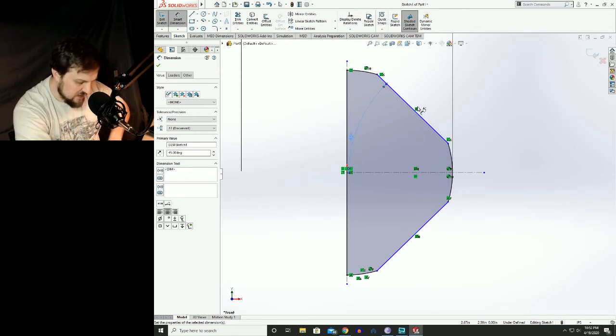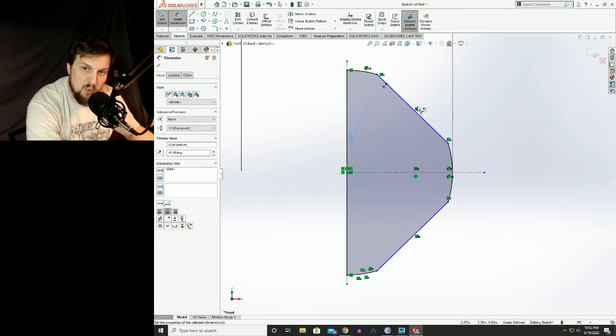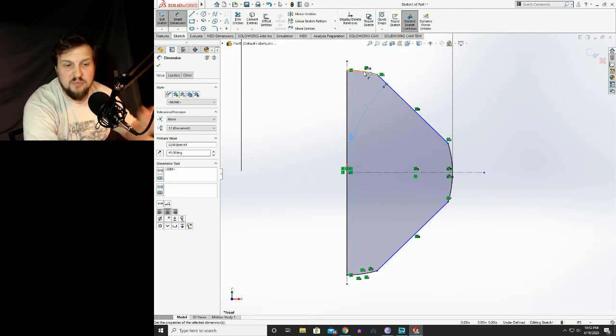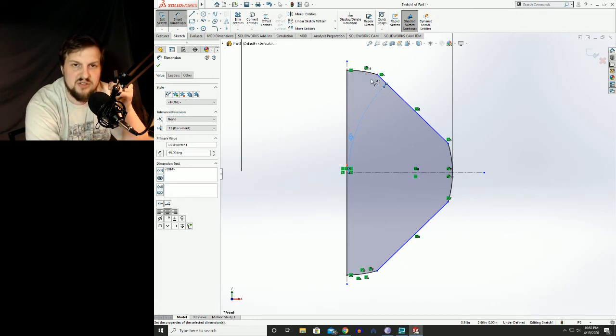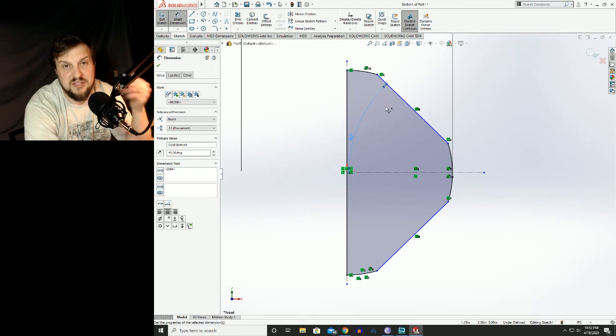And then if you look down at our book, this is the bottom of page 21-6. You see we've got 2 different dimensions here. They're both 1.75. However, the top one, the one up here, has an REF on it. We covered the reference dimensions, I believe, last course, maybe the lecture before that. But reference dimensions are dimensions that are specifically only there for reference, and they are driven dimensions, meaning that they're not driving dimensions. So you can't change that dimension. That dimension is a byproduct of another dimension.